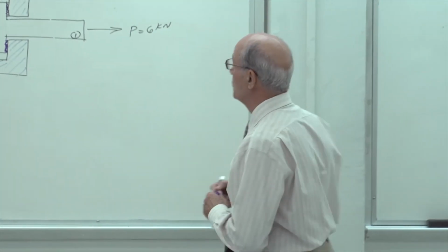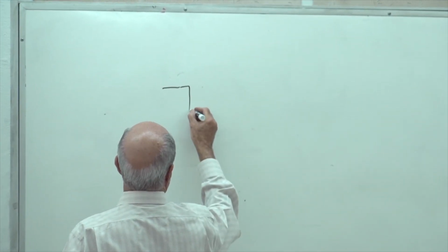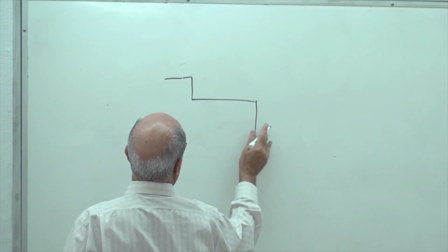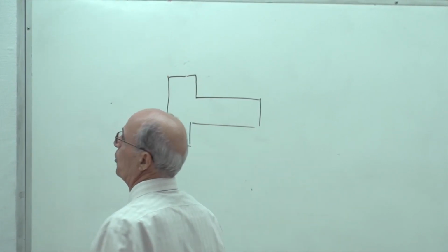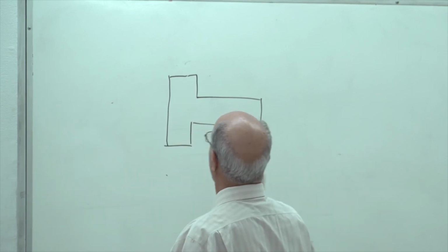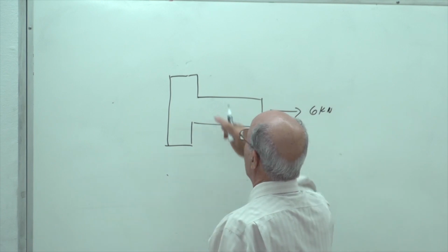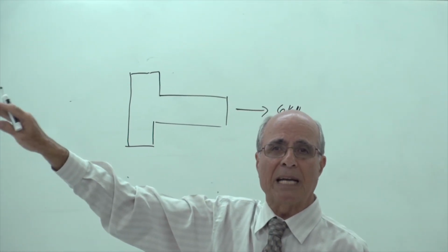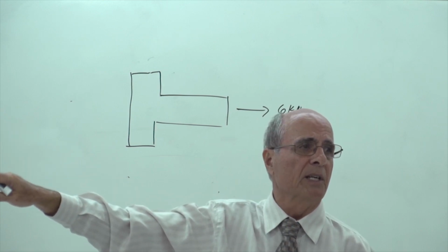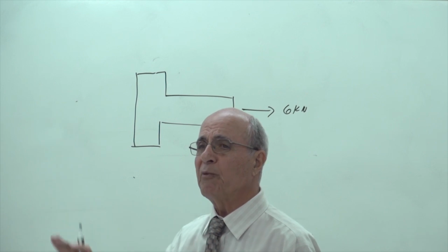Everybody understands that. So by doing that, or in any of your homework, if I draw that piece again, one more time, and I put the dimensions there this time. Look at this, this is piece 1. Is that correct or not? You are going to put here 6 kilonewton. Where is the touching point? The touching point is the maroon area. Yes or no? So at that time, I should have a force there. Yes? But they are symmetrical, top and bottom. So each one will get 3.